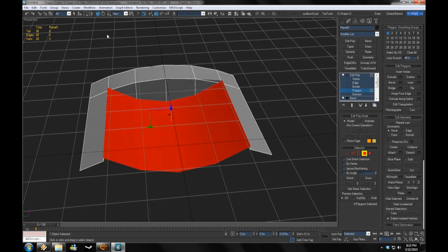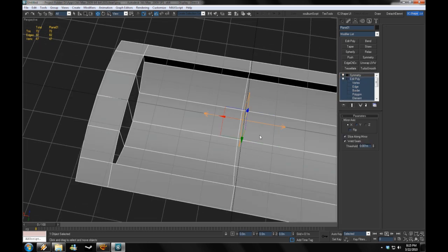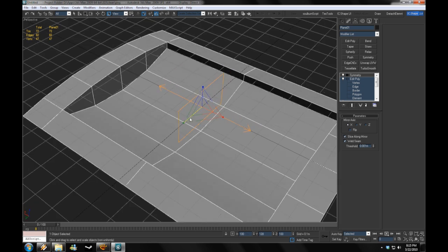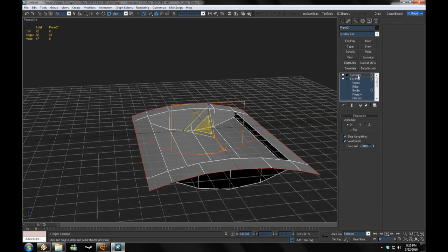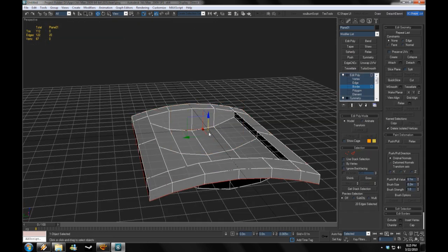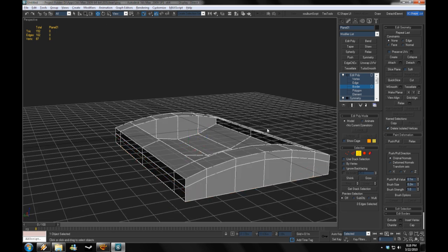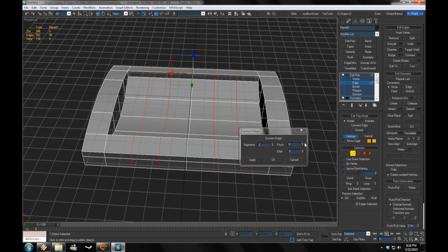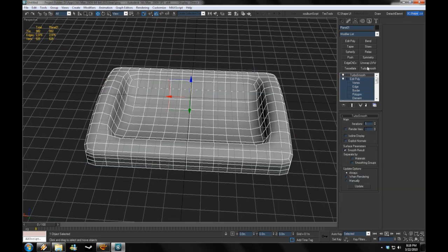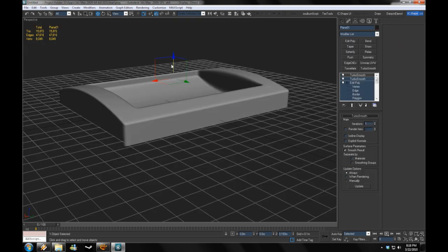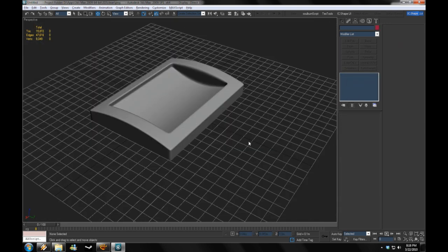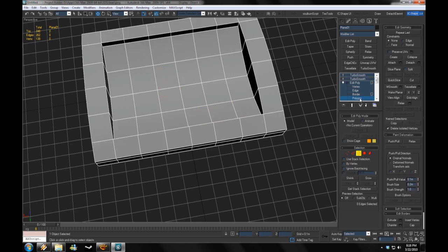I'm going to bridge it so it's all right. It's all modeled in. I'm using symmetry to get everything nice and simple so I don't have to do everything on both sides. So I'm going to get this outside edge by just using extrude. And then I'm going to be doing double smooth again. What a surprise. It's so easy.